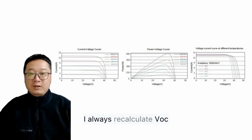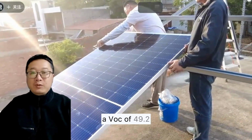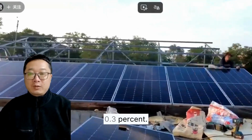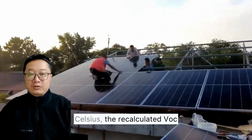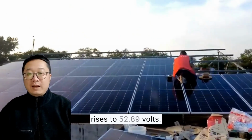I always recalculate VOC at the local minimum temperature. In this example, the 420-watt module has a VOC of 49.2 volts and a voltage temperature coefficient of minus 0.3%. When the ambient temperature drops to 0 degrees Celsius, the recalculated VOC rises to 52.89 volts.